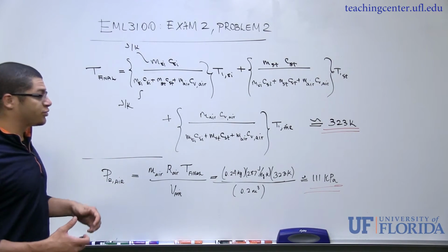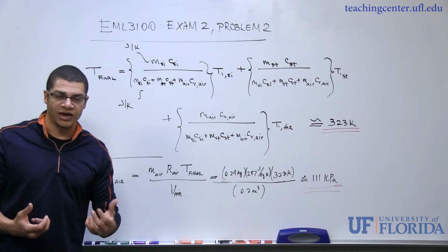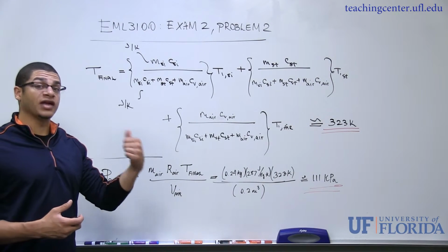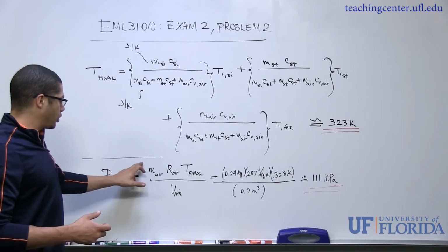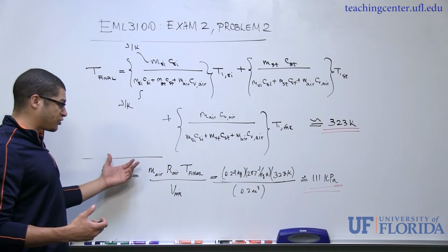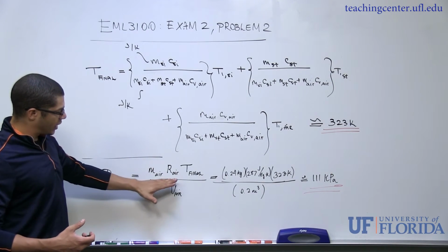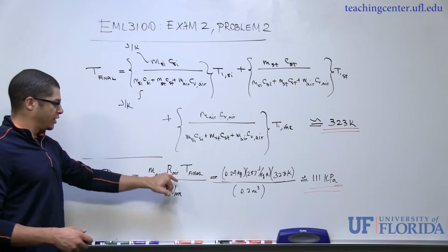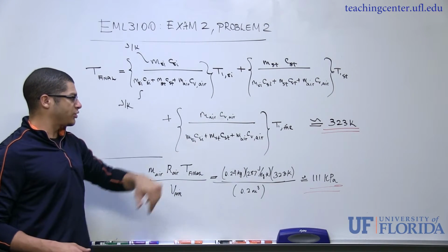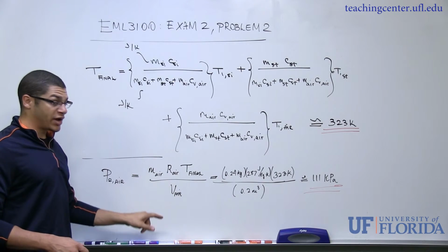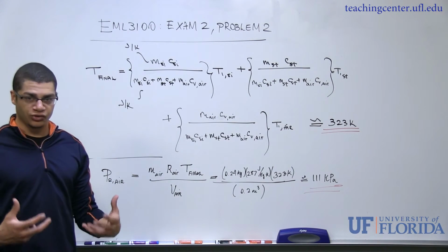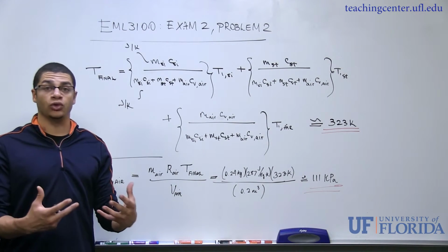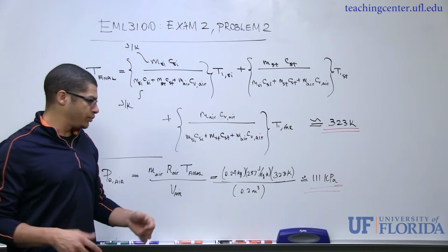And we can verify this by simply applying the ideal gas equation of state at state 2. We already know the mass of air, which hasn't changed throughout the process. The specific gas constant for air, this is a constant. T final, again, solved for above. And the volume of air also stays fixed. We constrained our thermodynamic process to be isochoric, or constant volume.